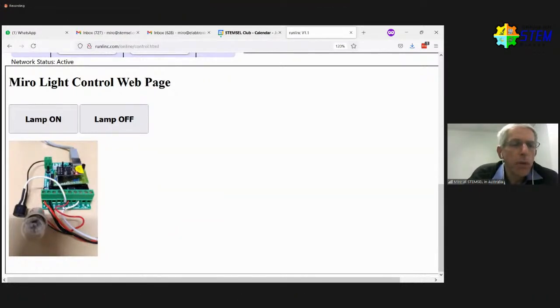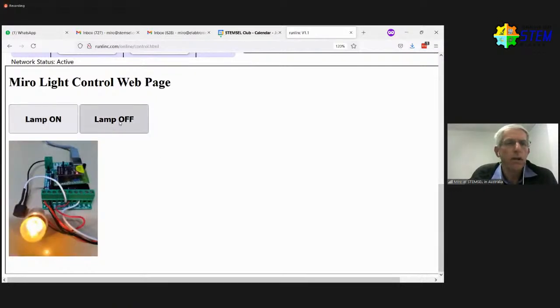You see the lamp and the wire, and it connects to a port here, C4. If we activate C4 to be digital out, then we can directly activate on and off the C4, which will activate a real lamp if you have this kit, the STEM cell kit. So that is changing a picture: picture on, picture off, lamp on, lamp off.